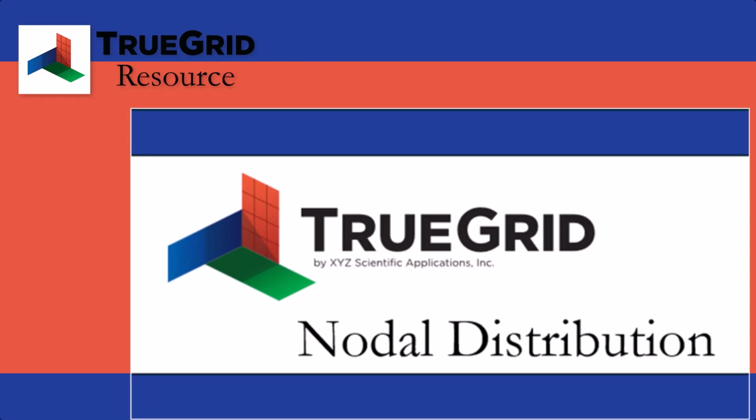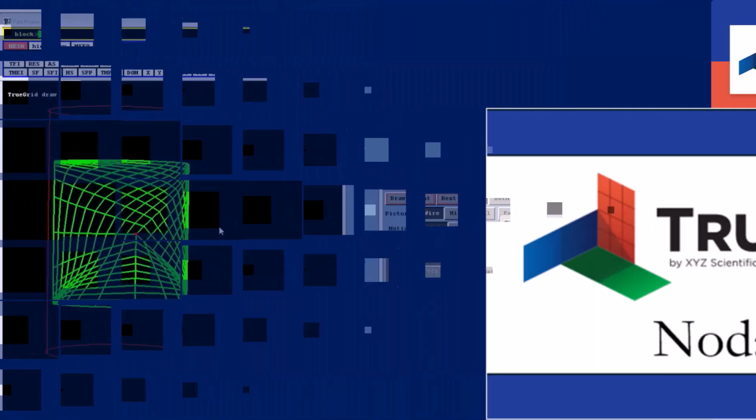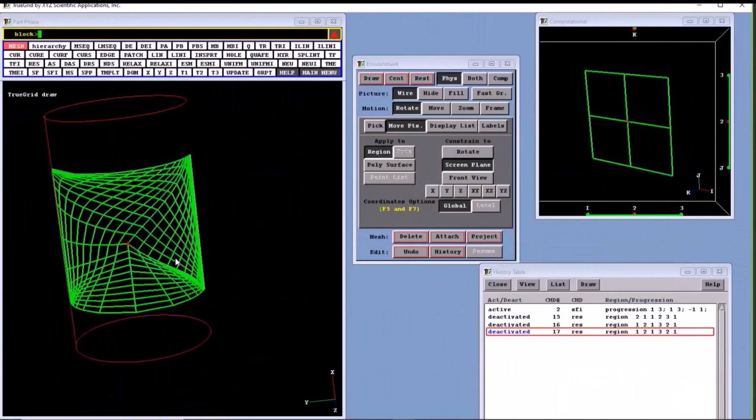For the next part of this lesson, we're going to use the model that we built in the nodal distribution lesson that already has nodal constraints on all 4 edges of the mesh that has been projected onto the cylinder. I want to show you some of the more sophisticated interpolation algorithms. These are going to be across the entire mesh. The edges are going to be the boundary conditions for the interpolation, and they will not be changed. So I'm going to start out with linear.